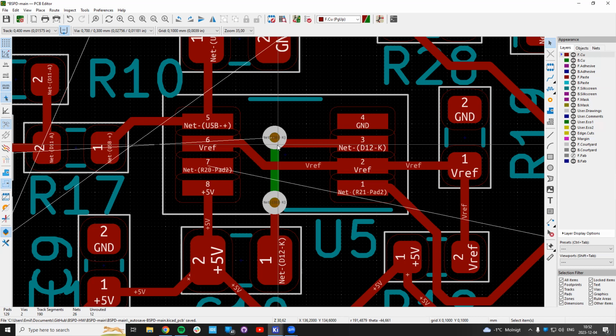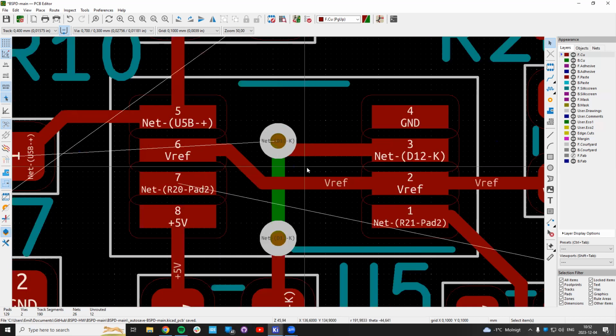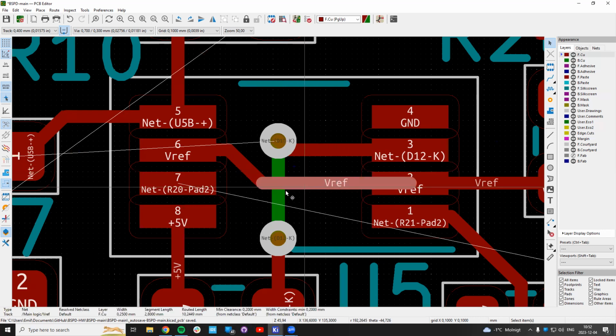So what we do here, having two layers next to each other, they will be quite spaced apart, but if they go underneath, they will also be pretty close. And there's no ground layer that's absorbing or isolating these two. So you want to try and keep the angles at 45 degrees because you have the right hand rule. So if you have a current going upwards here, if you show your right hand, you see how the magnetic field cannot really be coupled with this one because this is going in the 90-degree direction.